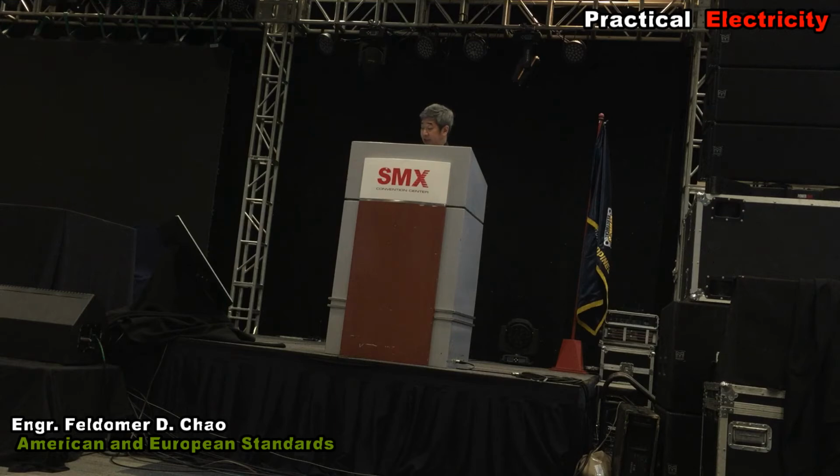Another is insulation. The American standards don't specify PVC for the medium voltage, and they don't have it for IEC either. On the other hand, they don't have tree retardant XLPE in their class, a class 3 XLPE and TR XLPE.